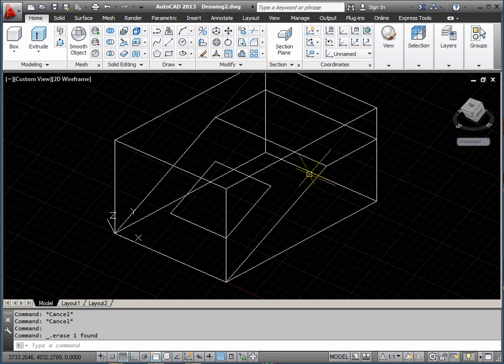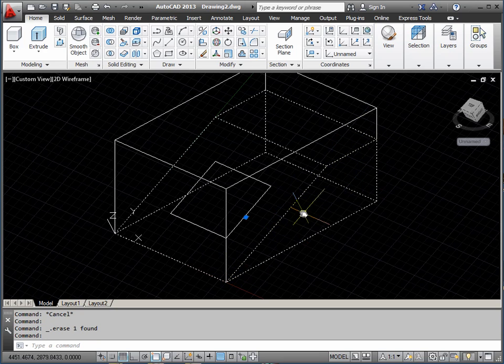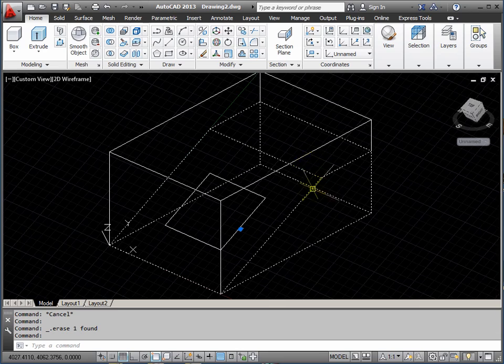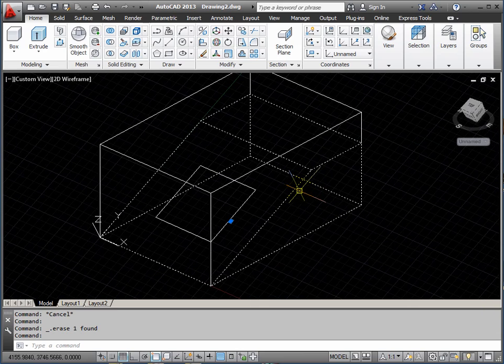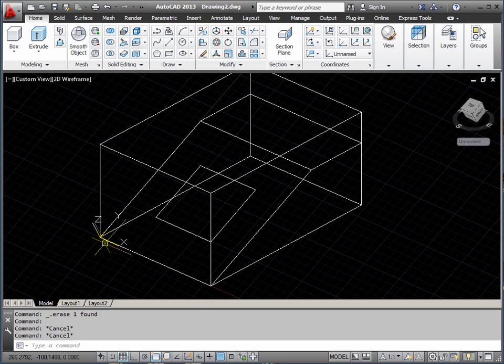Okay, so it's starting to take shape now. What I want to do now is shave off the sides here. I want to sculpt the sides a wee bit. This shape started life as a triangle here, so if I click on it, you can see there's nothing I can drag. I can't really manipulate that shape anymore. It's been disturbed too much. So what we'll do is we'll go back to the front coordinate system and draw a couple of triangles that we can pull forward and use to chop off the shape. So I'll go to the front UCS.